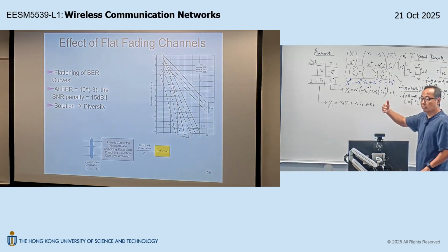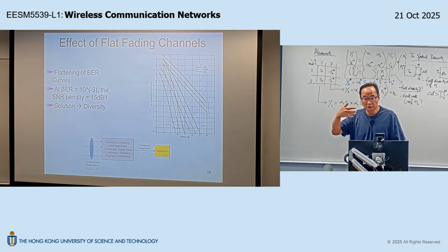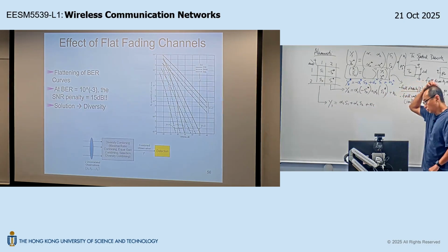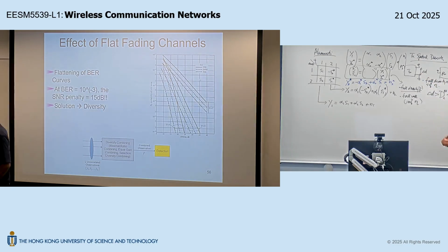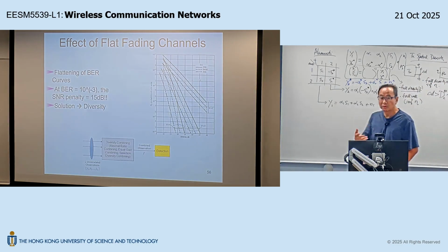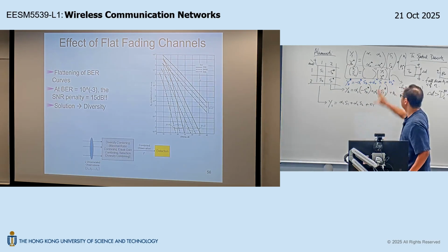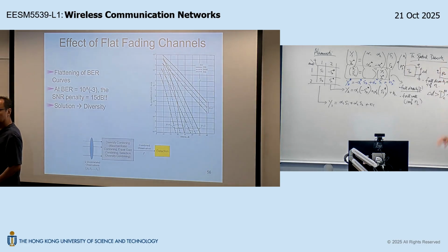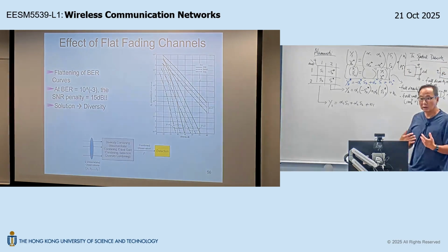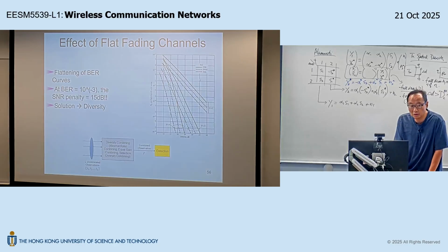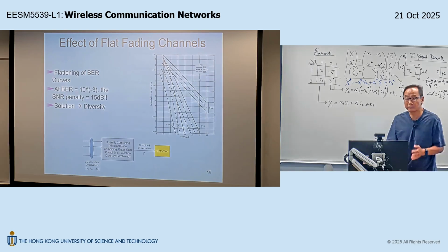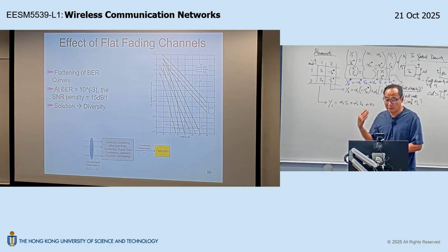But at a similar time to multi-code, which is in the late 90s, there is another way to utilize this multi-antenna system, and now it is called MIMO, multi-input, multi-output, and that was invented at Bell Labs, in fact, in the mid-90s. At that time, people figured out that if you have multiple transmit antennas and multiple receive antennas, there is something extra you can benefit from in addition to diversity, and that was called spatial multiplexing. So we will talk about that part later on.